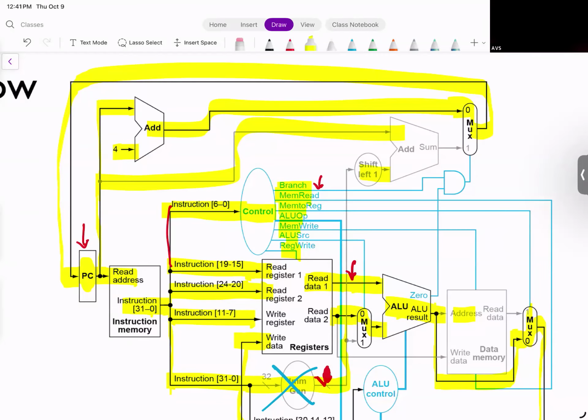And then by the next time that the next clock cycle comes and we open the gate again, all of these values are settled. If they're not settled, then you're going to run into correctness issues, okay? So your clock cycle should be wide enough and long enough so that you let these things settle down and all the values get updated, and then the new clock cycle comes, okay?